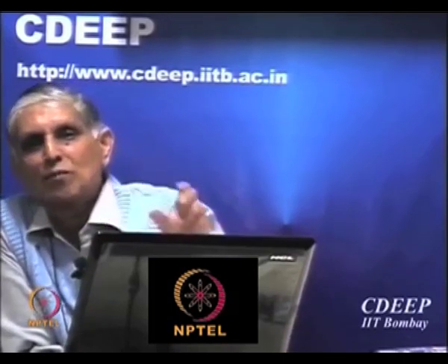So two lines are going, one data on this, one data on that, this may interfere with the next line close by because of coupling, due to mutual coupling, particularly mutual inductance. Okay. This is called crosstalk. It is particularly worse if one data is going in this direction and the other is coming in this direction; the crosstalk is highest, both amplitude opposite. So maximum separation. Okay. So that's a major worry: interferers, crosstalk, sensitivity to noise.